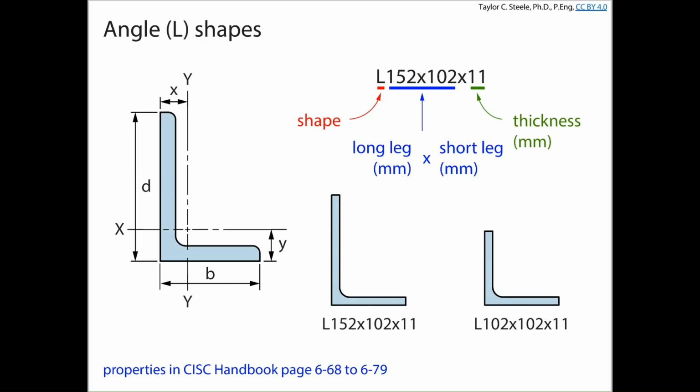in imperial measurements. What do you think 152 millimeters corresponds to as a measurement in imperial? Any idea? That's a 152 by 152 by 13. Any guesses? That might be a 5, actually. It is 6 inches, right? So 6 times 25.4 gives about 152 by 4 by something that's like a bit more than 5/8.